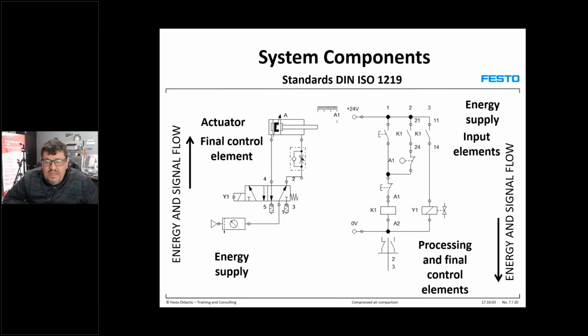That means you start off with, for example, in this case, line number 1. And the moment when we energize or press this push button, right, that circuit will be the start circuit, and it will follow as we go on down the circuit, what will actuate or energize next. All right, that means the electrical circuit works from the top to the bottom, and then you analyze it from left to right. Very important principle when you analyze a circuit, to understand how electrical and pneumatic circuits must be analyzed when you want to understand the working principle or the working philosophy of this machine.